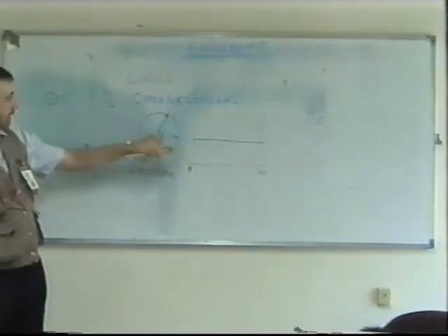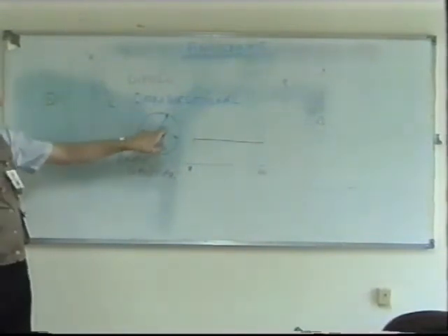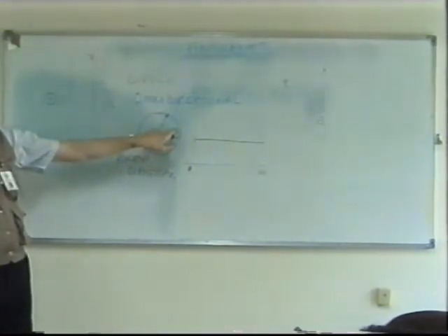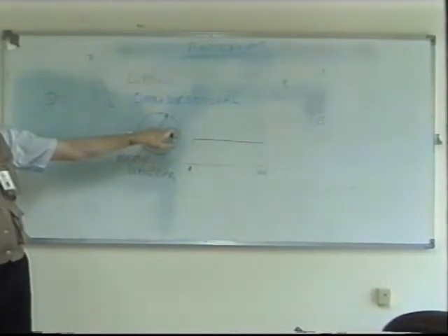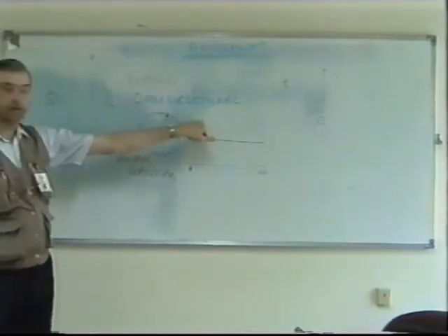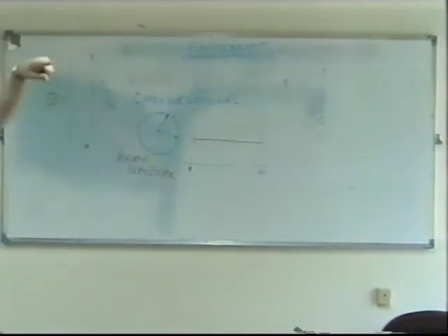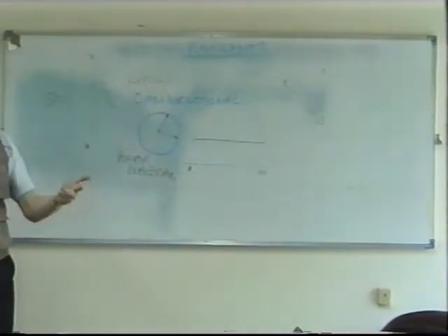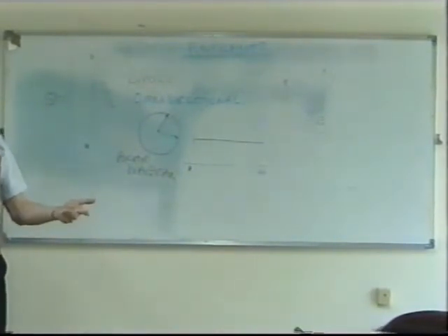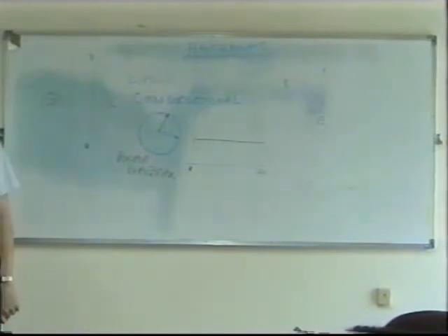But be careful with this indication. Don't get the idea that this represents distance or range. It does not. It just represents how strong the signal is. That's all. It doesn't mean to say that if you're here you don't receive the signal, if you're here you do receive the signal. That's something different. Remember, the range depends on line of sight for most of our communications. VHF, UHF and microwaves, SHF, they all rely on line of sight communications.